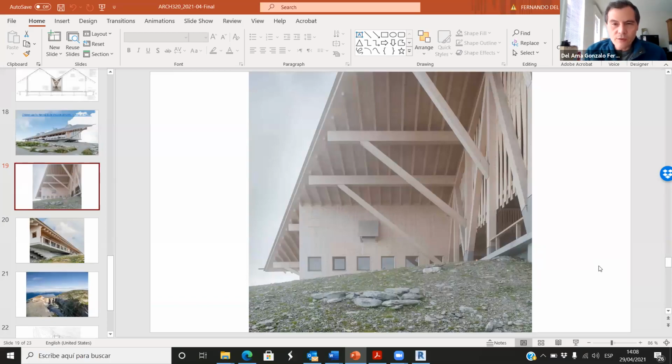Okay, so the first thing we are going to do today is to finalize this structural element. We created this truss. It can either be a truss or a component model in place, it doesn't matter. Then we need these huge beams here. It's not difficult because we just have to make sure that those beams are on the vertical elements of this truss. And then we need to create this beam system.